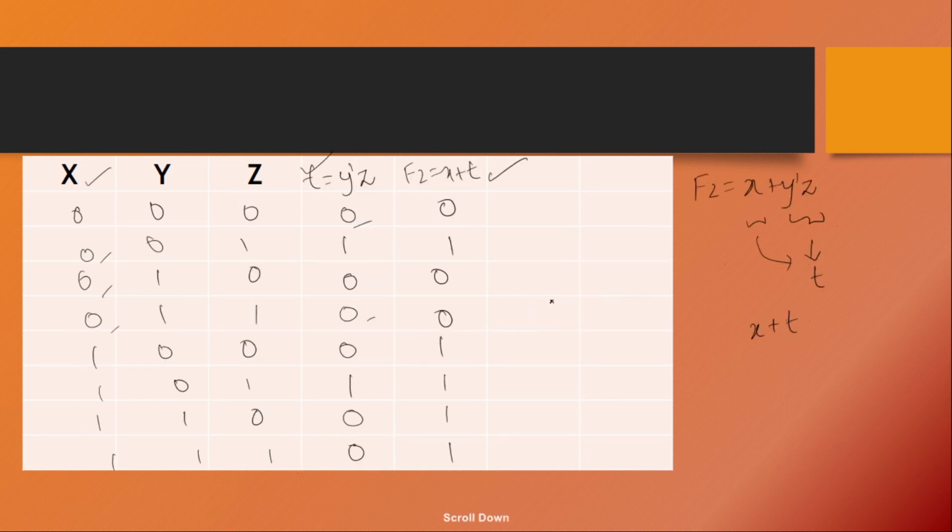Let's take this to the next example. Let's say you have this truth table and we are not given the expression. They have just given us the truth table, and they have asked us to find what f is with the help of this truth table. In this scenario, the whole table is formed and given to you. You need to find out what the function is. So what we can do, you mark all the ones inside the final function column.